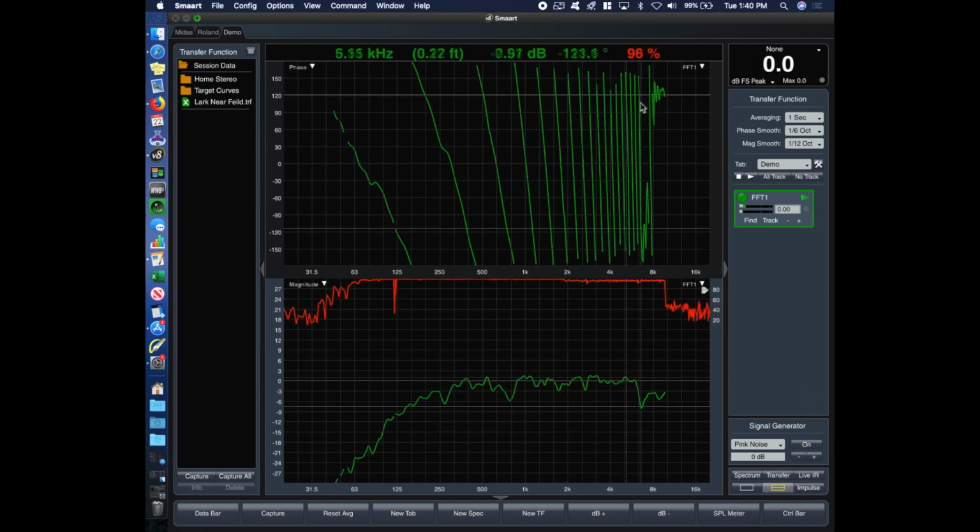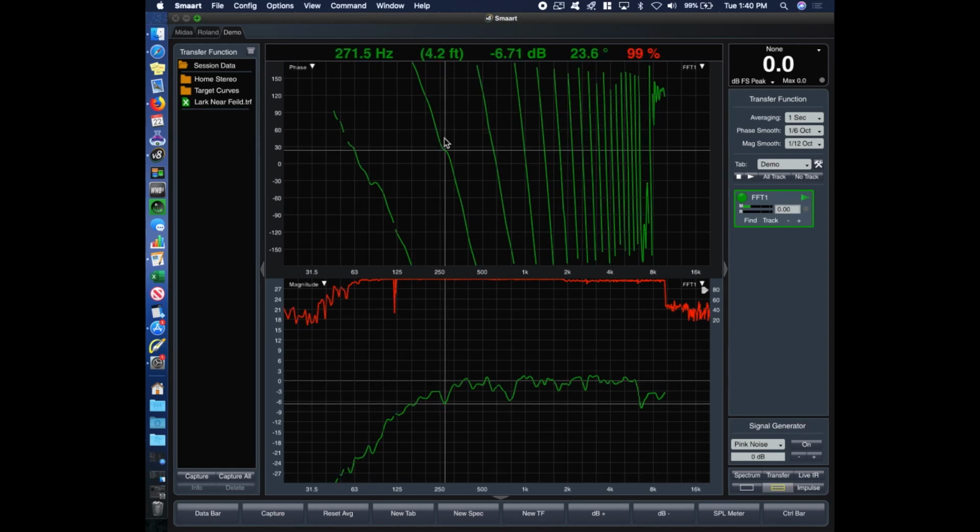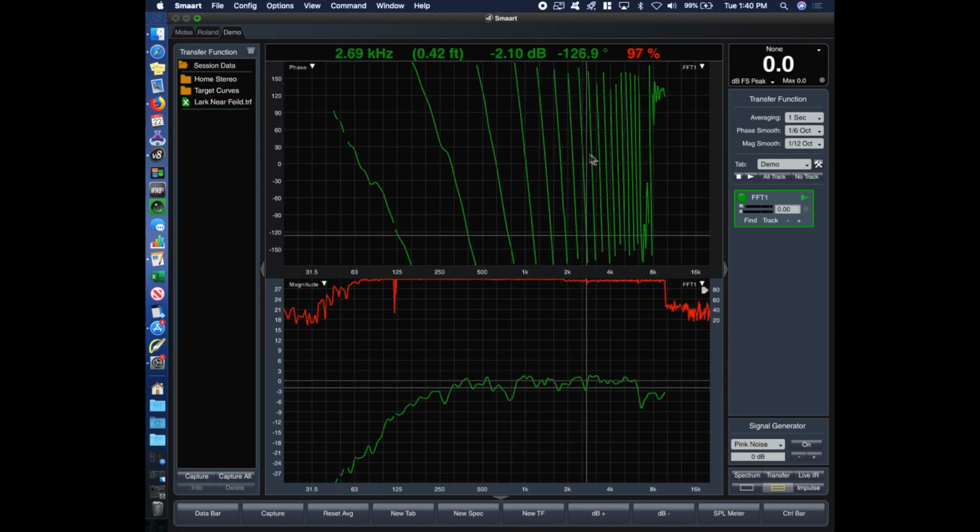So we see here with this phase how it's all hacked up and really jumbled there. What that's showing us is that there's still a time offset here. We need to use Smaart to calculate for the internal latency of the computer, the I/O device, and the console. Just the whole round trip latency to go from the computer back to itself.